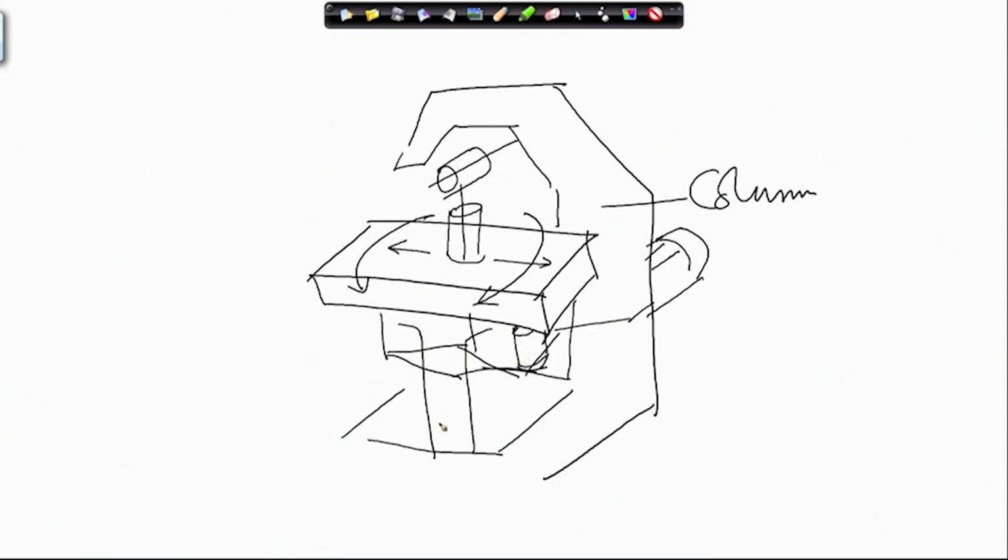Why is this required? If you want to rapidly position the job at some location, you cannot depend upon the slow machining feed rates which are available from the machine. There you put this motor on and apply the automatic motions that you require, and the overrunning clutch will make sure that the motion derived from this motor will prevail over the motions obtained from this one.